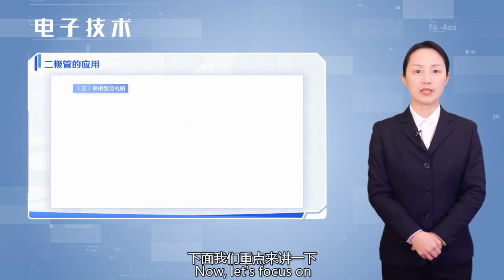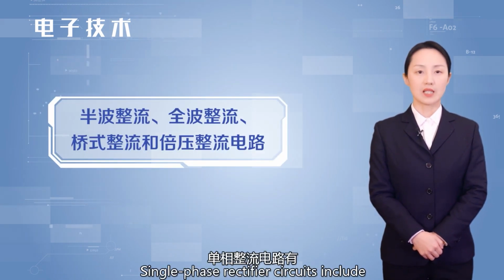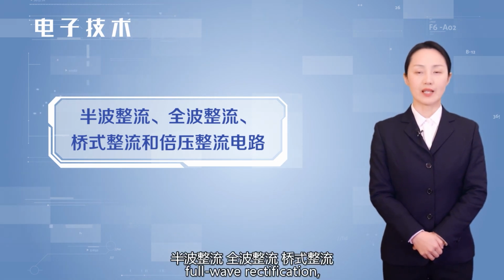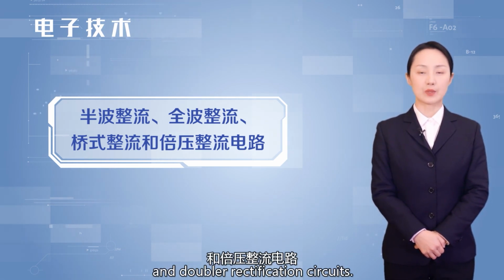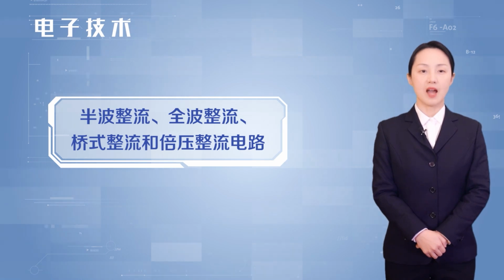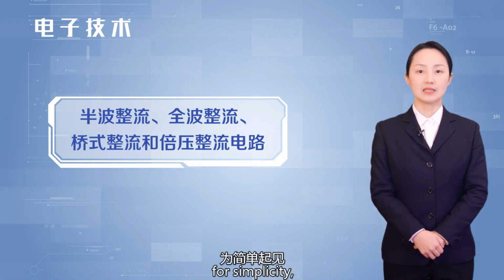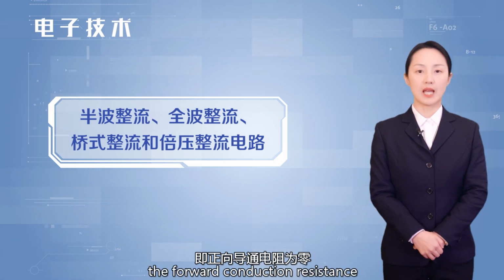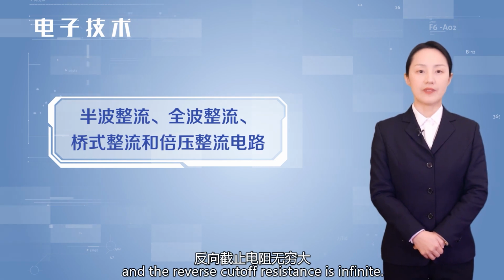Now, let's focus on single-phase rectifier circuits. Single-phase rectifier circuits include half-wave rectification, full-wave rectification, bridge rectification, and doubler rectification circuits. When analyzing rectifier circuits, for simplicity, diodes are treated as ideal. That is, the forward conduction resistance is 0, and the reverse cutoff resistance is infinite.